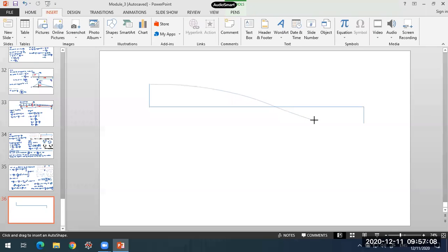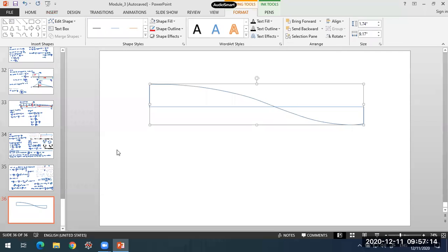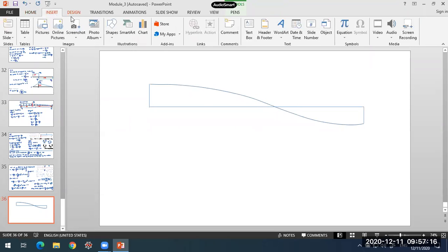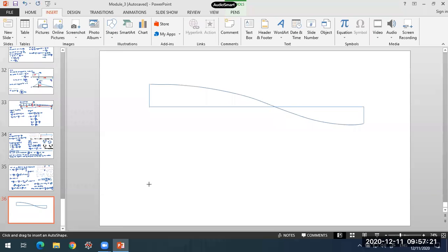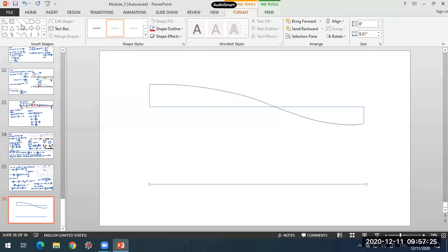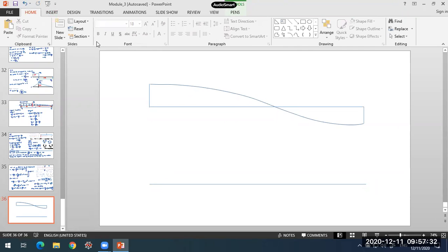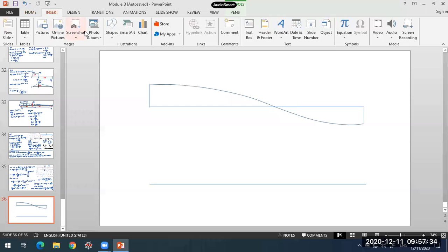So here in this case, we are coming across variation of shear force in a quadratic manner. Okay. So this will be the shear force diagram. And in case of bending moment diagram, the bending moment varies cubically. We don't have to plot any cubic curve exactly, but the variation equation says that the variation will be in a cubic form.